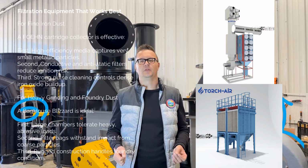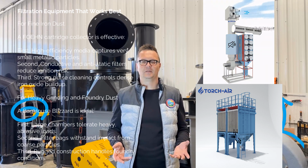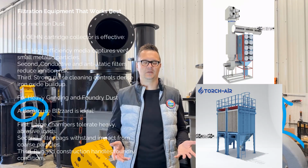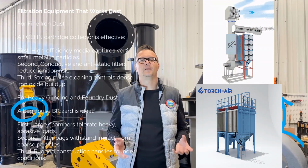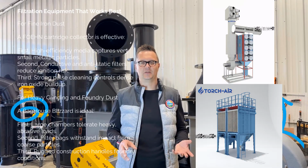Filtration equipment that works best for fine iron dust. A cartridge collector is effective. First, high-efficiency media captures very small metallic particles. Second, conductive and anti-static filters reduce ignition risk. Third, strong pulse cleaning controls dense iron oxide buildup.